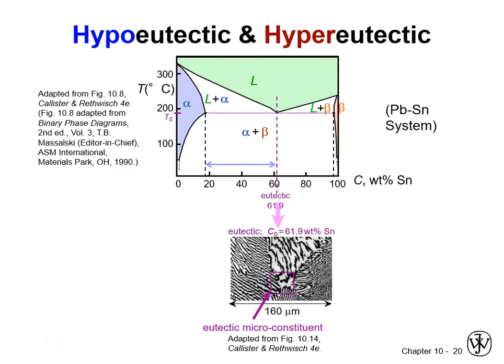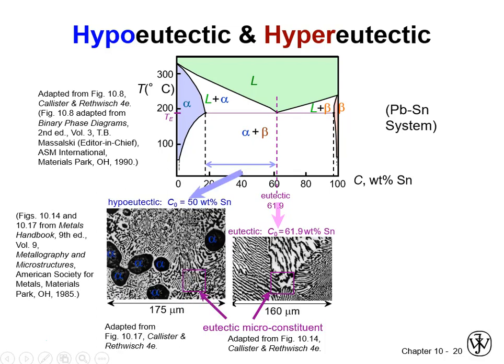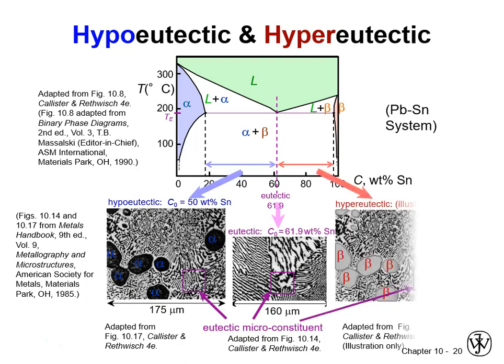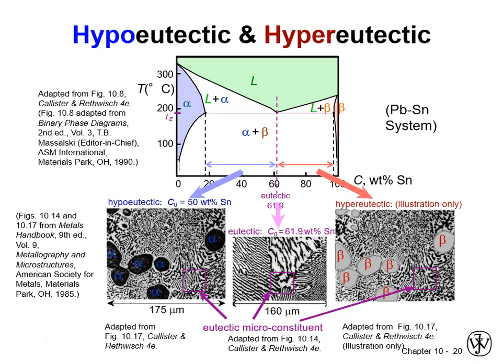And so this animated arrows shows those two regions, along with the type of microstructure we would expect to see. So in this case, if you follow the very pale blue arrow, you can see that we're getting primary alpha that forms in that liquid plus alpha region, and then all lamellar eutectic for what happens to the remaining liquid once it goes through the eutectic transformation.